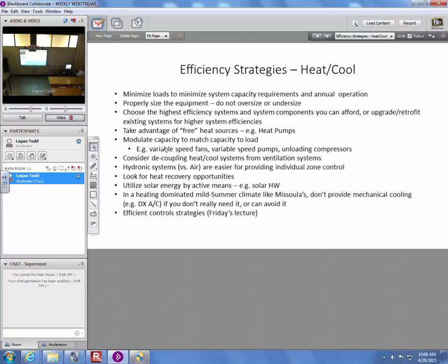Even in residential, a lot of hydronic systems like radiant floor tend to get installed as cycling or binary systems, because modulating valves, modulating dampers, modulating pump speeds and modulating fire rates on combustion equipment are more complicated and more expensive. It does work better, and it's much more common in the commercial world. But even in a radiant floor heating system in a building, you'll tend to see zone pumps that just cycle on and off, or solenoid zone valves that open and close instead of modulating. Doesn't that affect the comfort of it?